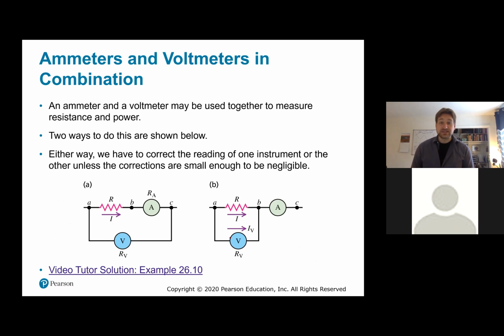And the presence of that resistor in the voltmeter, say, is going to affect the reading by the ammeter. It's going to affect the current flowing through that particular branch, because some of it will have diverted this way.